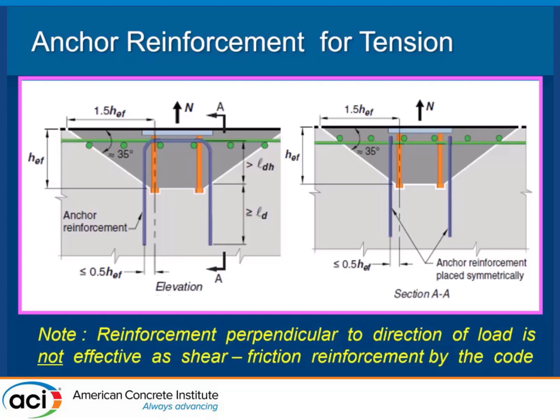And you get about a 10 to 15% boost in your values. So if you're designing in the top of a pier, which we'll talk about a little bit later, and I've already got vertical reinforcement, my longitudinal reinforcement in my column or my pier, and I can put my anchors in, it's there. I don't have to even use it, but I can call it supplementary reinforcement, and I get a 15% boost in a concrete breakout calculation.